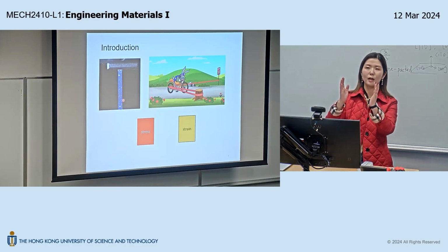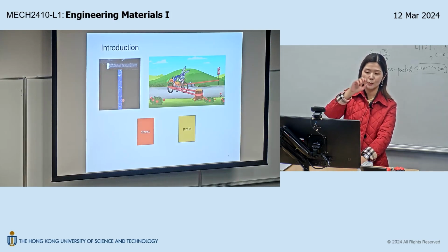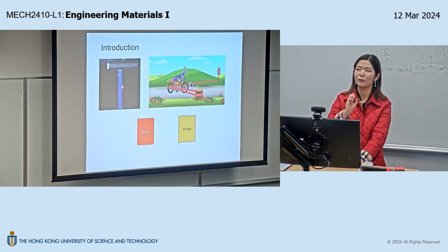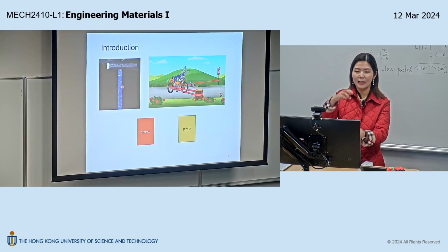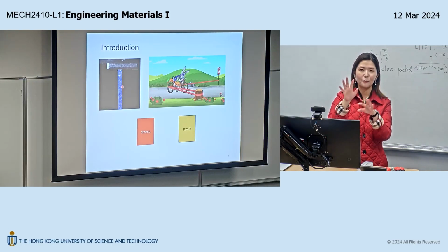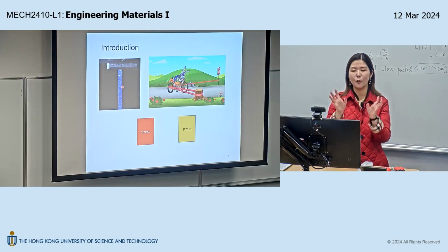We set up a camera, and while it is loading, we have some spray, and this spray will form a random dispersed particle pattern. That's some ink. We call it a speckle pattern. And as you can see, if we load it up, this speckle pattern will get further away, stretched and deformed, right?